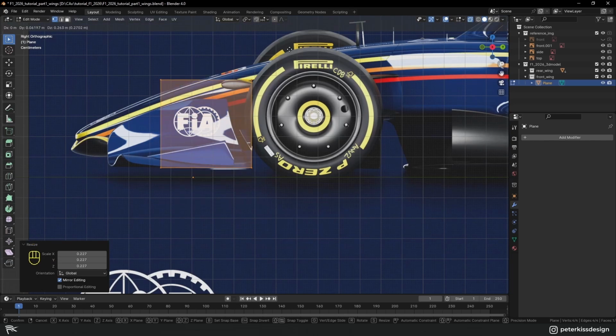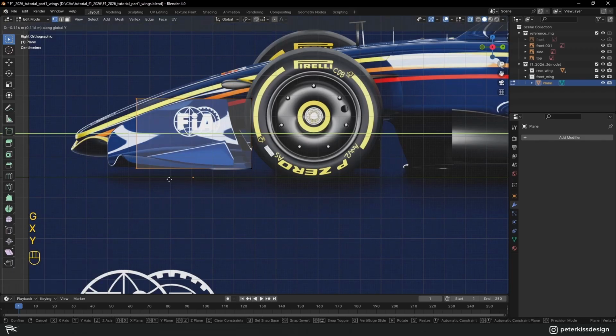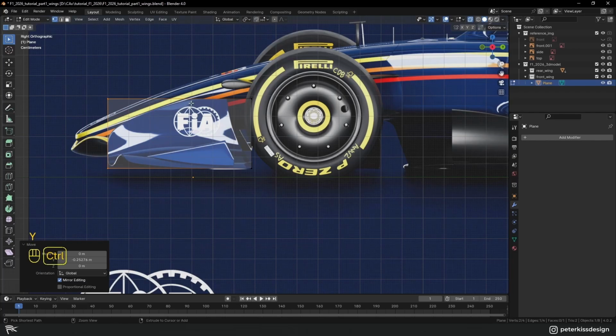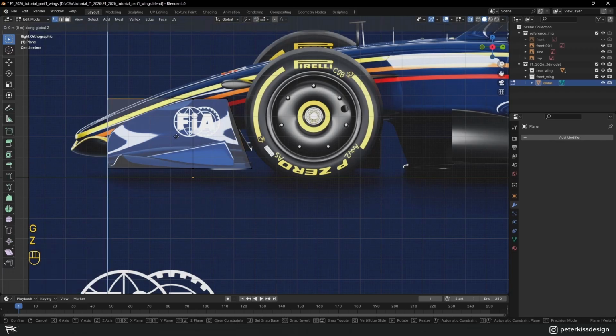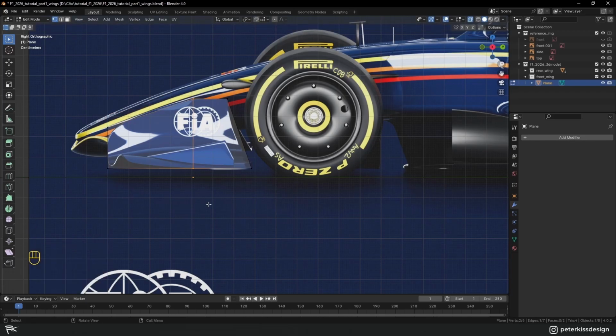It's all about repeating the same steps so you remember that. It's the same as in the back, just play with the vertices. Let's add a loop cut here and create this shape. Select this corner, slide it up with double G, then move this front corner to the bottom, then add one loop cut in the middle and move this back vertical to create this shape more concave.